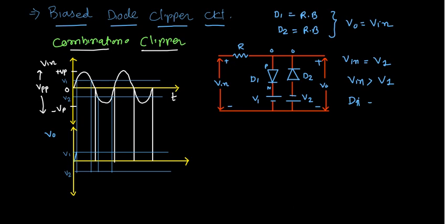is forward biased, because this value Vp is higher now, and this is lesser now. So at that point D1 is going to get forward biased. We are considering an ideal diode. This is nothing but an ideal diode because nothing is given as silicon or germanium. So at that point, what will happen if D1 is forward biased? This V1 is directly available at the output side.